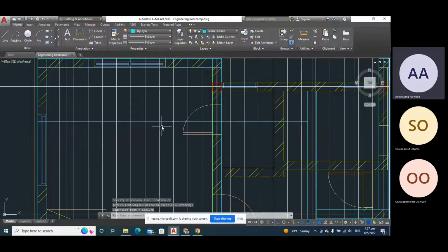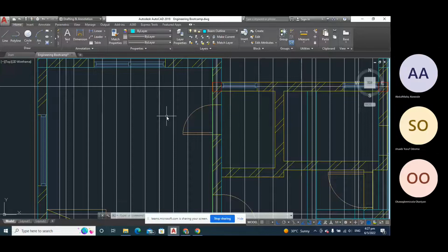This is 6.8. Now, when you are doing your roof layout, you consider, okay, when the carpenters are placing their planks, is the space between your beams going to be enough for a standard length of wood that you have for your roofing system?